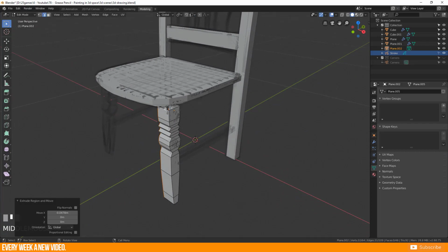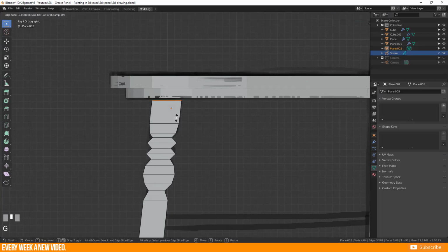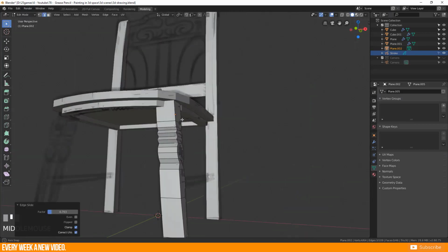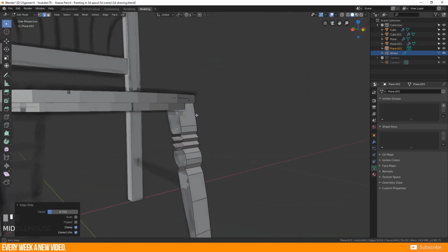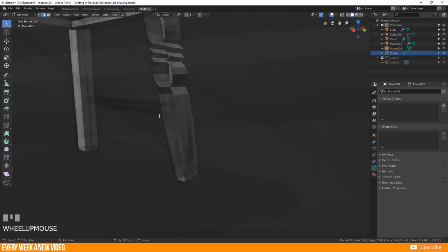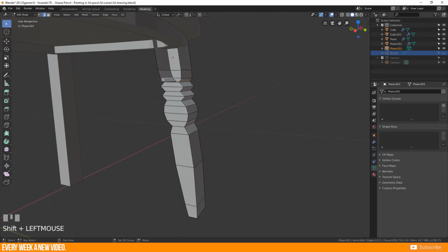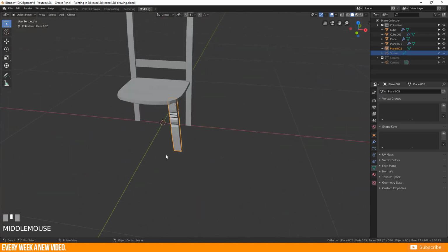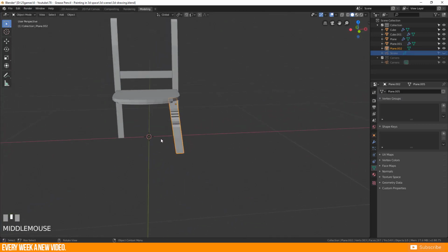We have here a hole right now, but I will just select this and move it to the top part with edge slide and Alt to the direction. We just need to fill it again, and the sketch is disturbing our view. So let's quickly do this. I'm filling just those vertices. See that it is closed again. Sorry, I selected the wrong edges. So need to care about this, and everything is fine. Well, and this for sure should be mirrored as well.